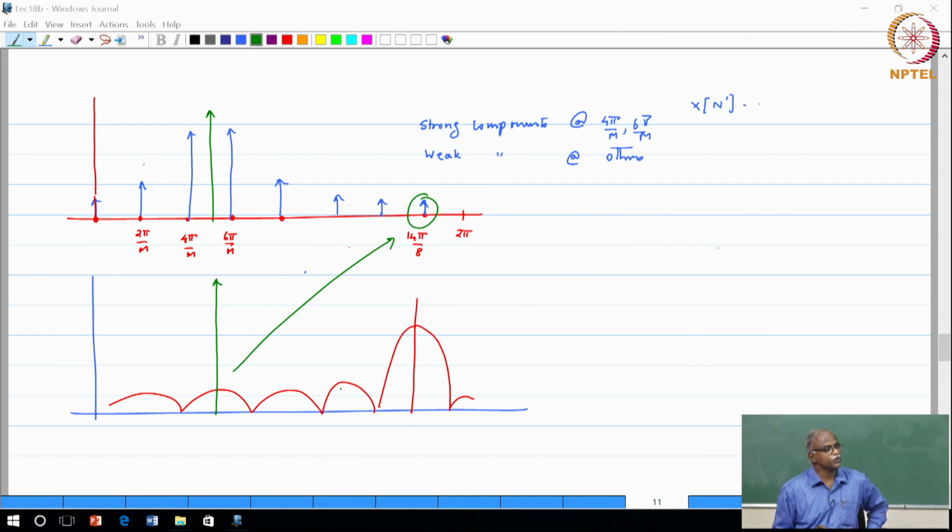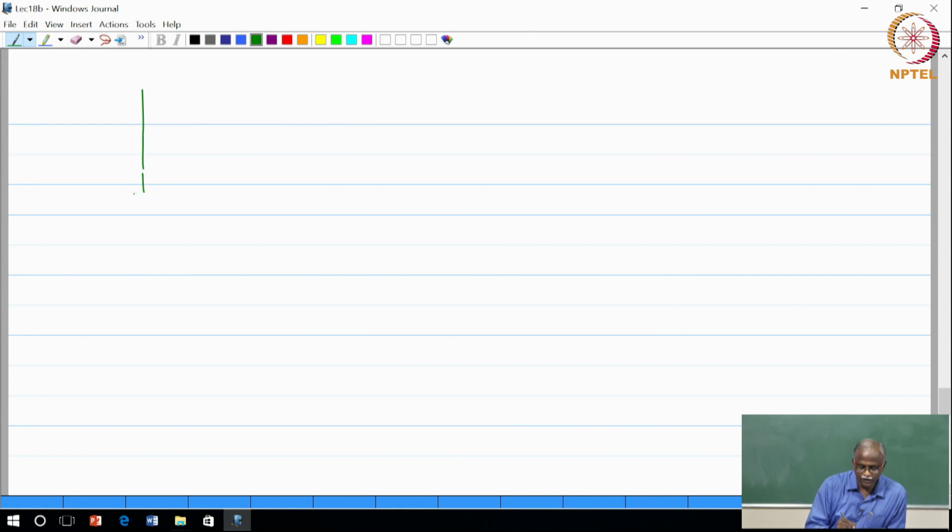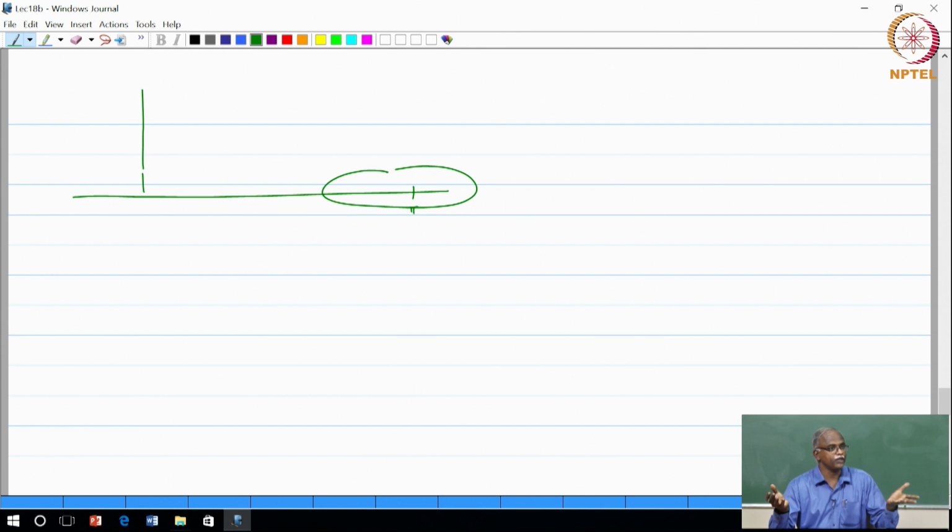Why is the spectral lobe so high? If you go back, this is the frequency response. If I were to plot the frequency response of an impulse response or any signal, this is pi. If I see a lot of energy around the high frequencies, which basically means that my frequency response has components all the way from DC to pi, that indicates that there have been some sharp transitions. Usually sharp transitions are the ones that cause that.